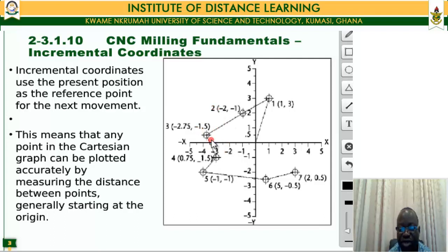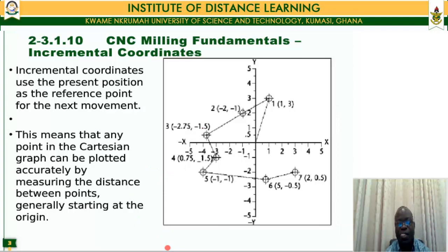If you look at what we have here, it's -2.75. So if you have this as minus position -1, and then this position is -3.75, then you ask yourself, okay, from -1 to -3.75, the difference is -2.75. And so it is taking its coordinates relative to the previous coordinate. That is what is called a relative coordinate system. Okay.